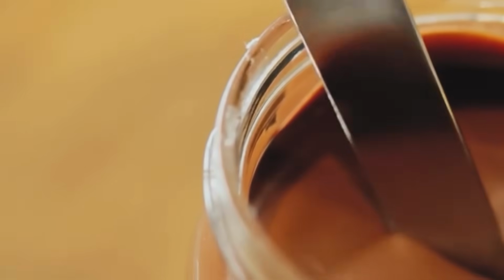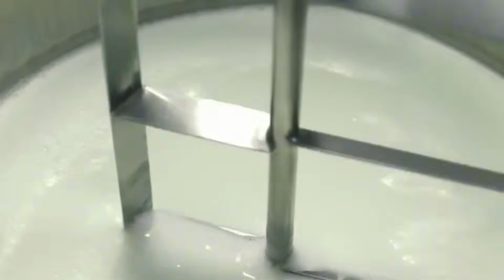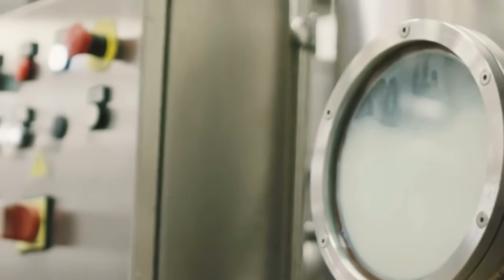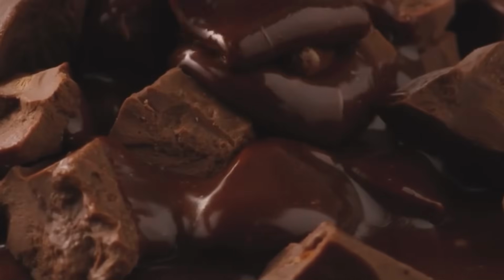Following cooling, a pre-molded wafer lid is applied to seal each filled shell. These lids are formed from the same dough and are baked separately on a synchronized rotary system. A robotic arm equipped with vacuum suction cups picks and places each lid onto the open cavity. An edible adhesive compound, typically a glucose-based syrup, is applied to the perimeter edge to create a bond. Pressure rollers compress the lid and base together for mechanical adhesion.